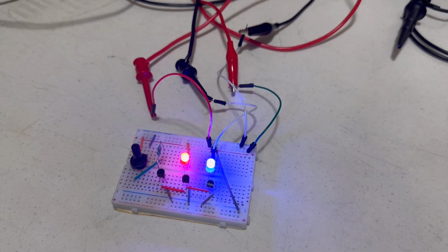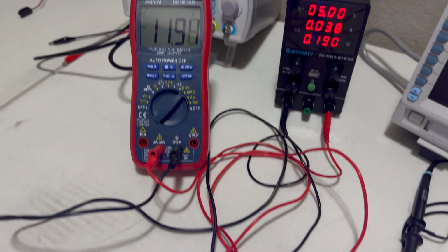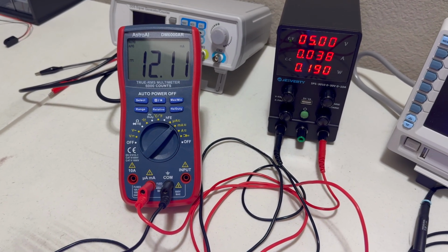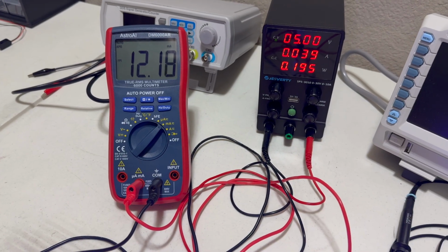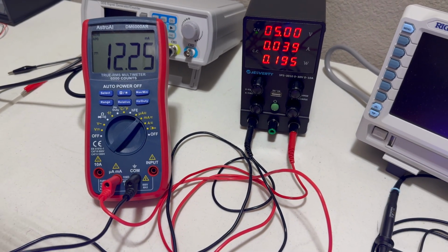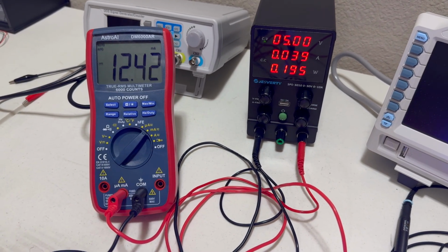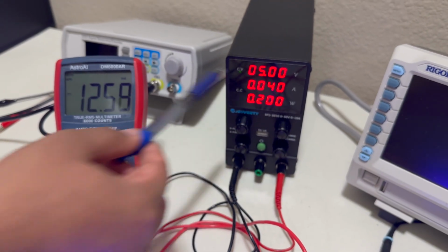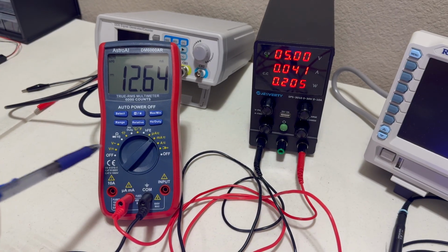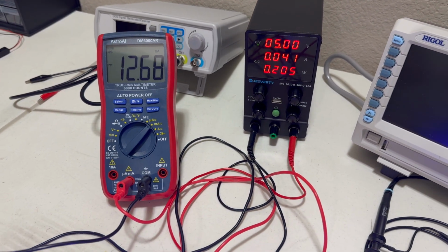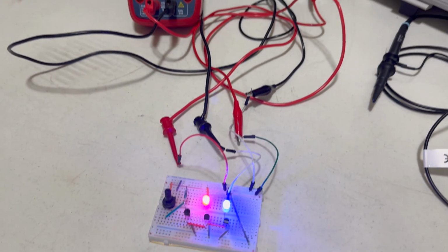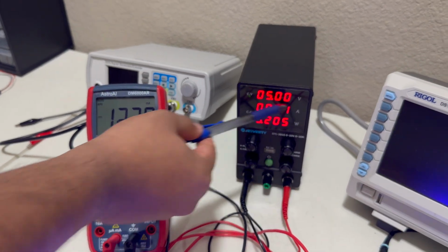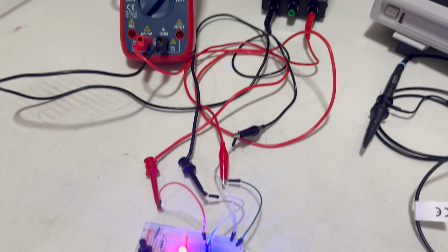And that'll keep going, and now the LEDs are glowing at their full brightness, and this goes to right around 12 milliamps. And then we can see that the reading on this meter is about triple what we're seeing from one branch, because there's 3 branches. There will be 3 times the current in the entire system. So this is measuring one branch, and then this is measuring the entire circuit.